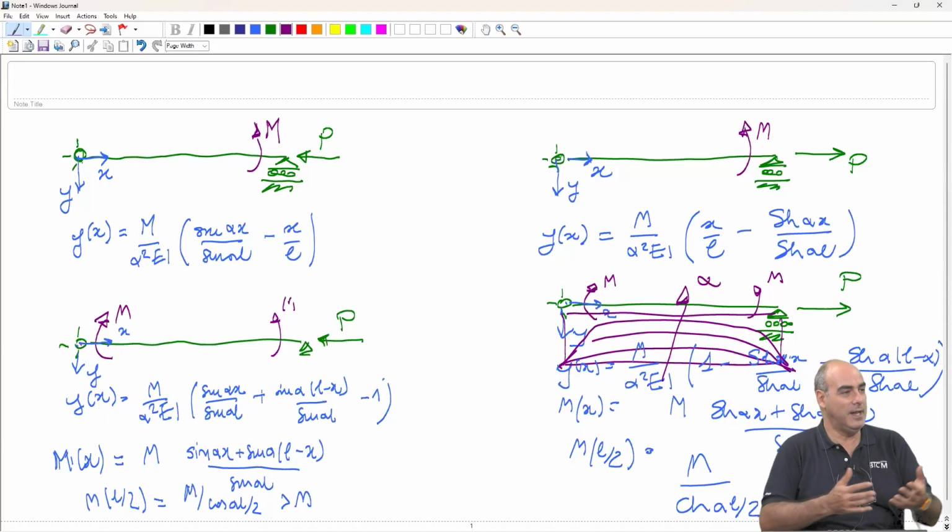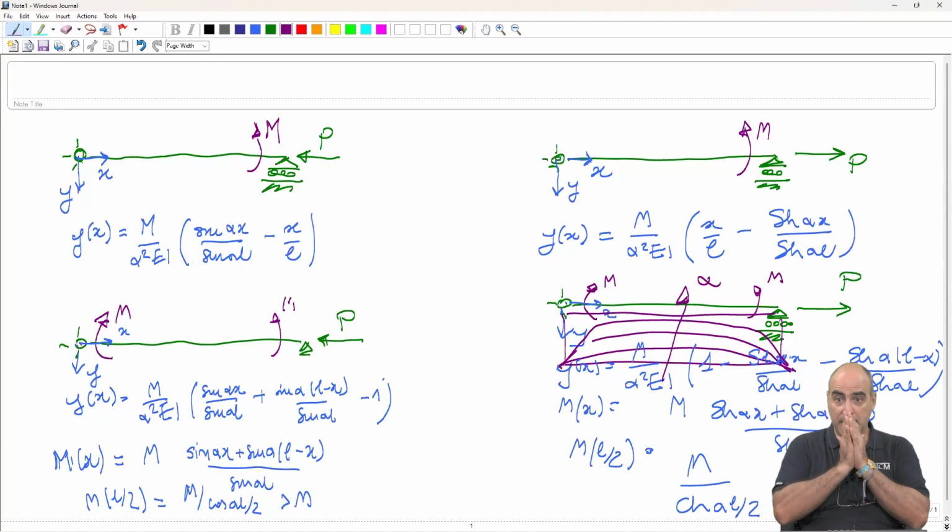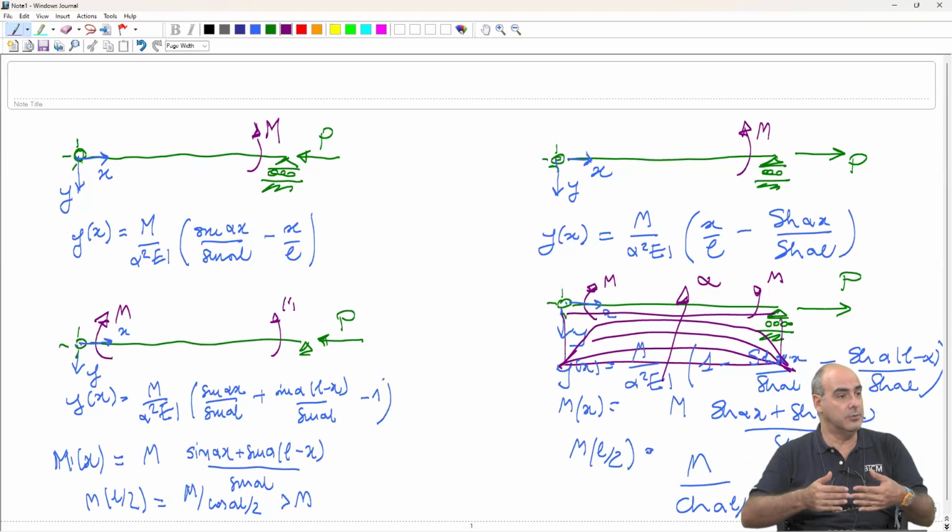You have the self-weight plus the weight of the water they absorb. So they are gravity loads. They induce a bending moment. So you are asking an element which has no flexural stiffness to resist flexural actions. And how do you impart to a rope this flexural stiffness?